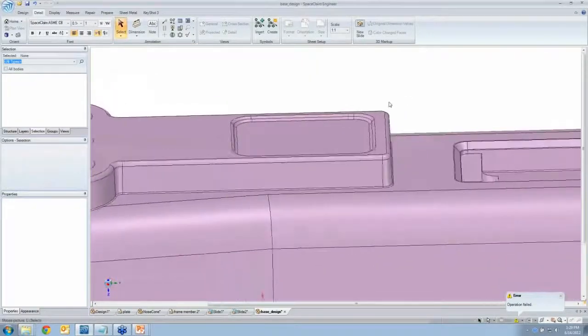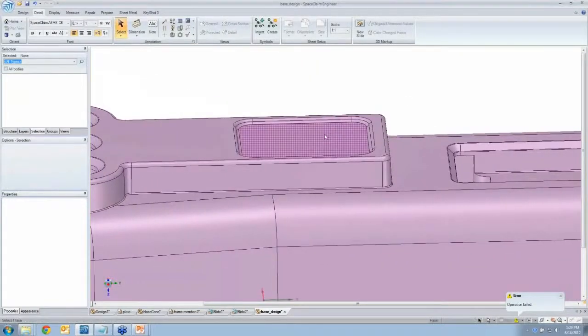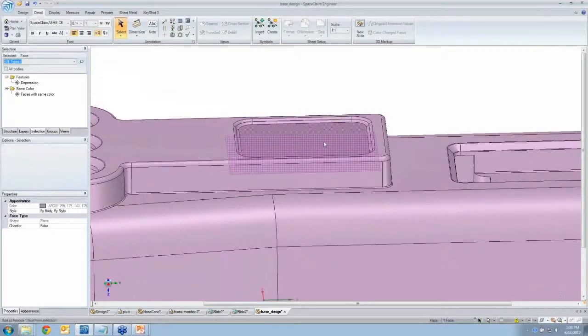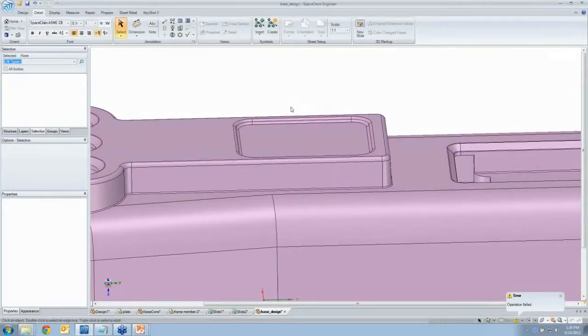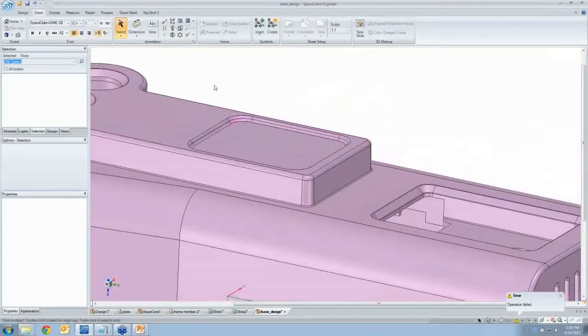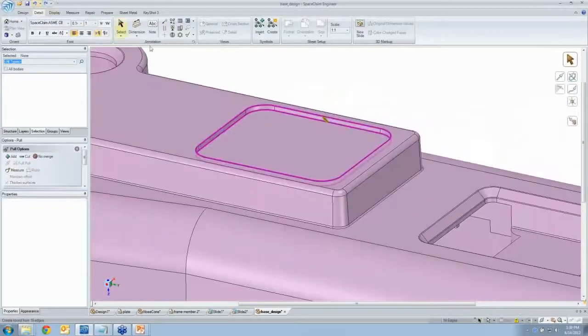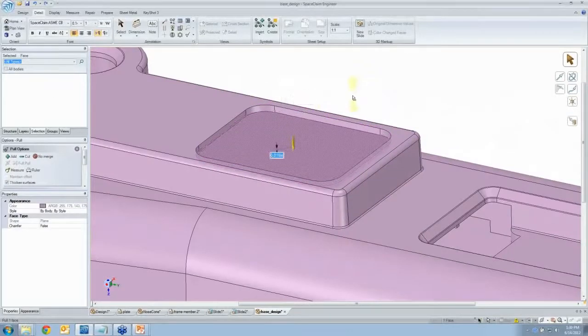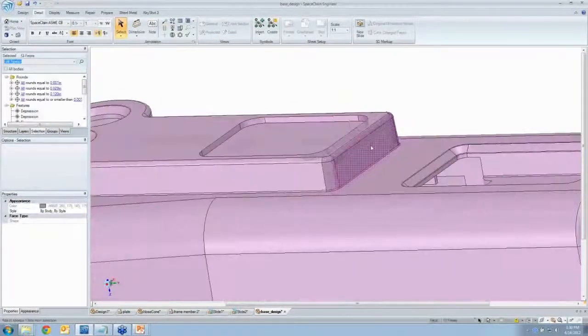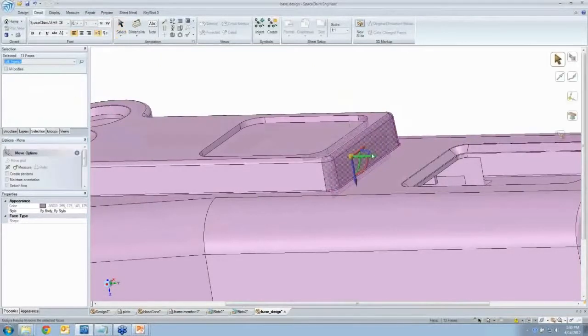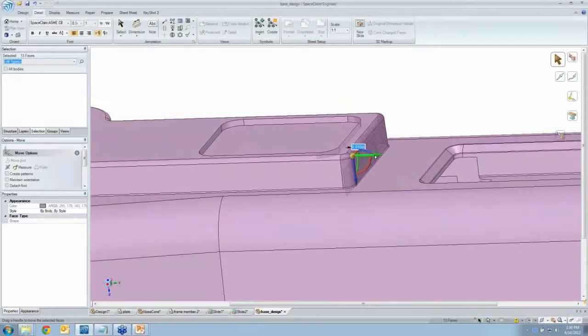Now, I accidentally selected something wrong, but I could move this thing up and down. I probably need to get the face below it if I'm worried about the thickness of it. You know, and sometimes I can't. So right there, I wasn't able to make a change. You know what I would just do though is probably fill in those faces and just get rid of them. I'll just undo it for a second and show I could move that thing up or down and change the depth of it. In fact, I might just try to move it right now while those rounds aren't there. I mean, rounds can be problematic anywhere. They're complicated, but we give you the tools to either undo what you've done or fill them in. There we go, and then go make those changes.